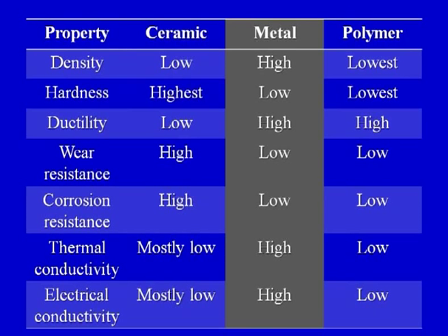Metals have low hardness as compared to the ceramics, and therefore they can be processed easily. One metal can be used to cut another metal. The only condition is the hardness of the cutting tool should be greater than the hardness of the workpiece material. So metals can be machined, but machining of ceramics is a bit difficult because of the very high hardness of the ceramic materials.